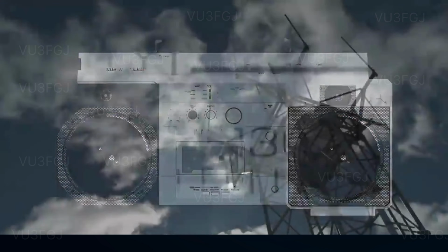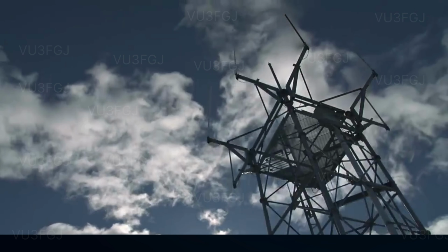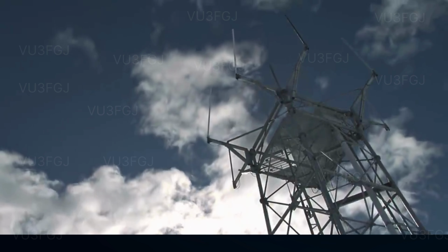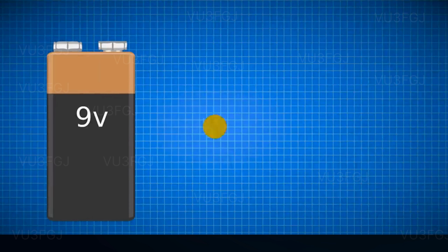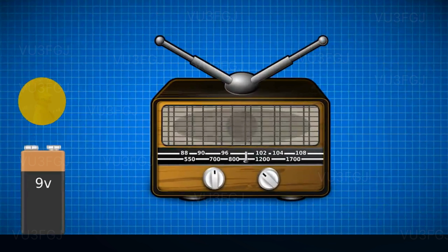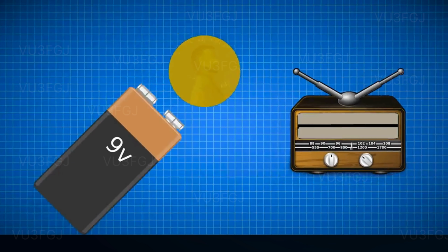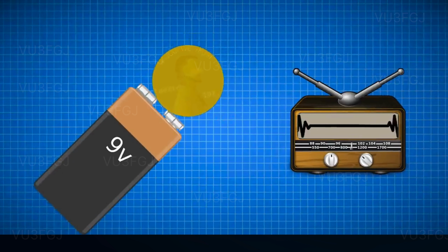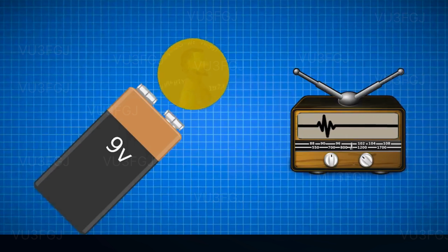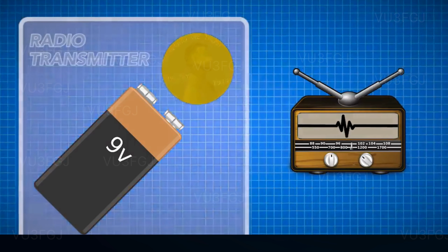As a demonstrable introduction to understanding what radio is, we'll engage in a simple explanation of how you might make one. All you need is a battery, a coin, and an AM radio. Tune the radio to a static channel and start tapping that coin on the 2 terminals of the battery. You'll start hearing that tapping through the AM radio. By doing this, you'll have made a crude radio transmitter.